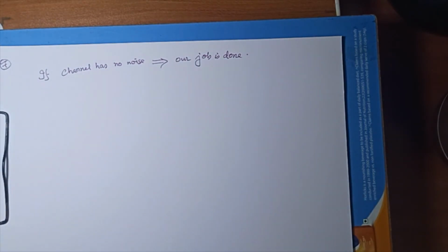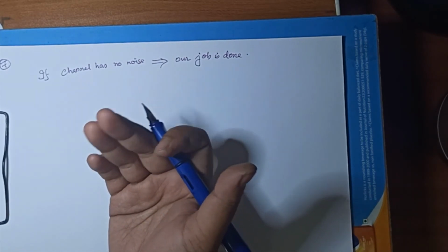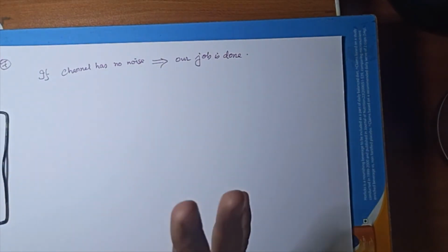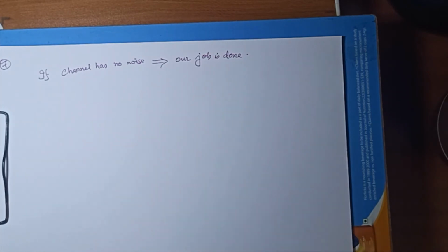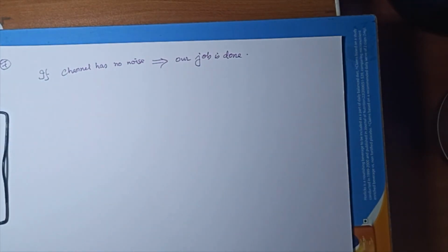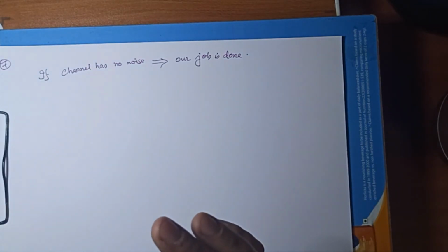That will take a huge amount of time. But that is fundamental in both analog and digital communication, and you have to do some equalization for that, right? To have a nice unit amplitude and linear phase response kind of filter. To have the channel behaving like that, you need equalization. So that thing is understood.